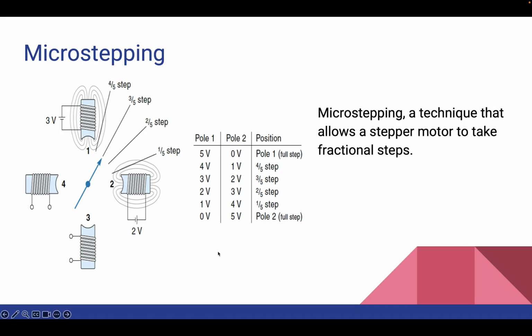And the second important point is that the actual position of the rotor in a microstepping system can be highly dependent on the load torque. So careful consideration is basically made to the design and operation. And one significant benefit of microstepping, particularly for delicate systems, is its ability to reduce the vibrational shock often associated with taking a full step.